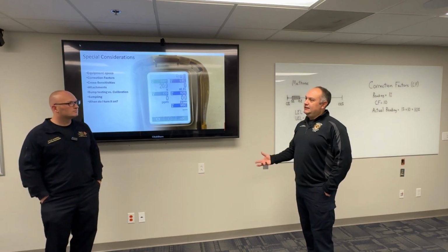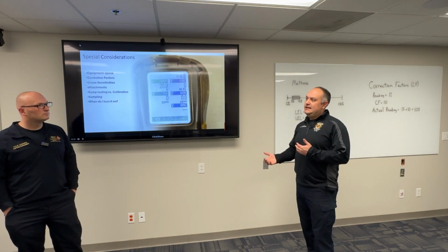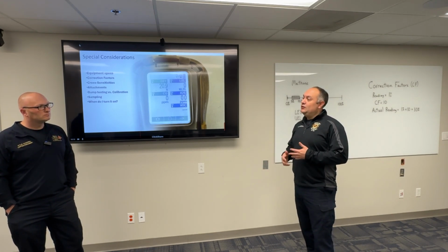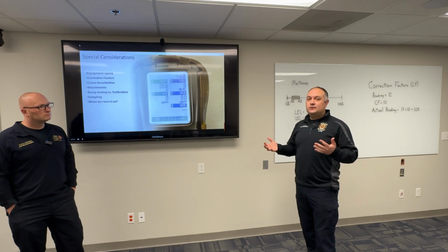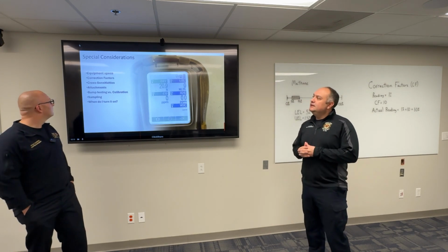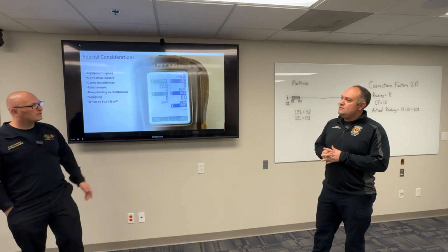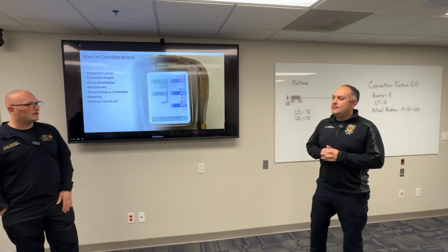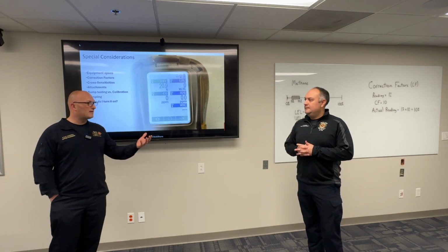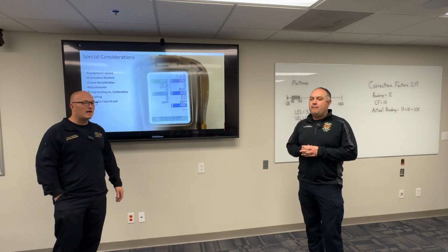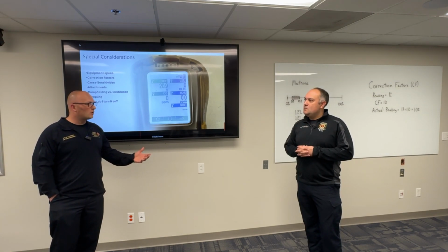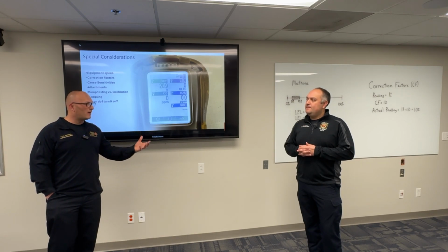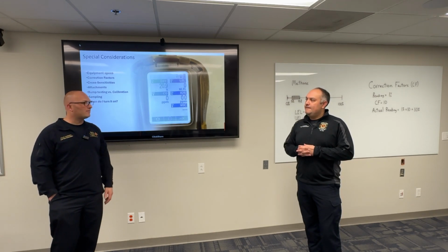If it's not in your manual, you can look up a technical note like I talked about before, and that should be in there. You can probably find that on the website, or if you ask your sales rep, he or she might know as well. Cross sensitivities, I think we talked about that quite a bit, just really knowing what might give you false readings or give you something else. Like, if I'm looking for CO, I might not have CO, but I might have something else going on. Exactly. I've had that on a few apartment complex calls where we showed up and there was no gas, but that CO alarm was going off for something, and you just have to go around and really dive in and try to figure it out.